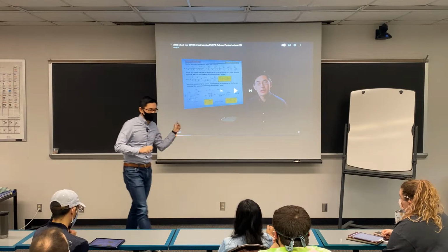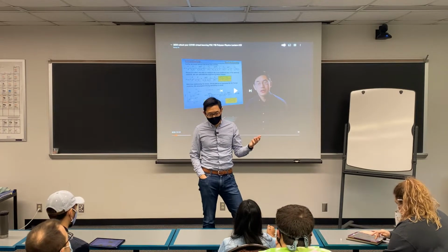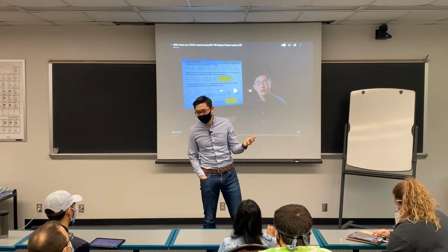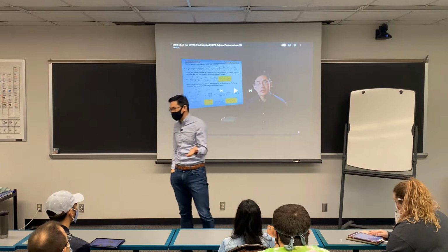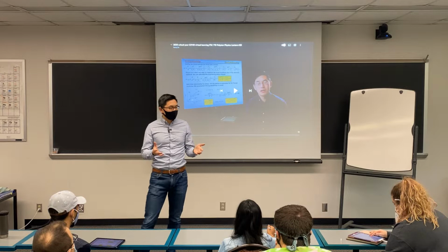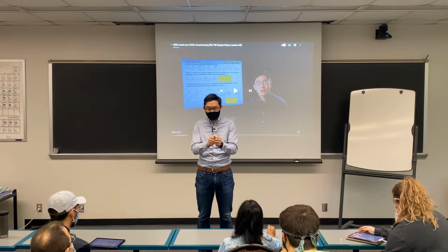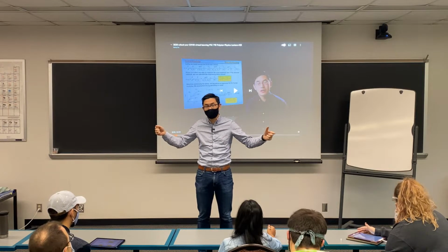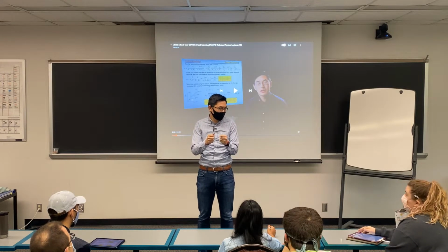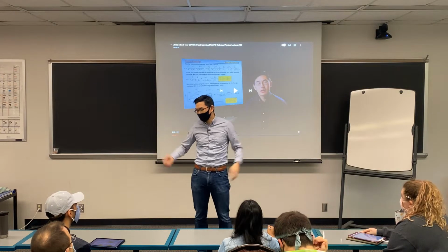The first part, as I mentioned, is more like the evolution of rubber elasticity theory. If everyone recalls, we made a few assumptions in the last class. Those simple assumptions give us a very unique capability: they allow you to see how much force you can expect when you stretch a rubber twice or 3, 4 times, because of loss of entropy.